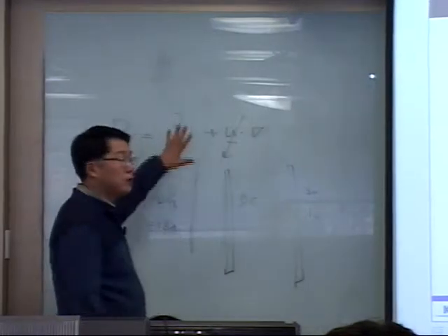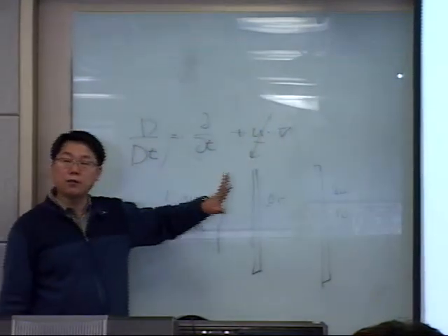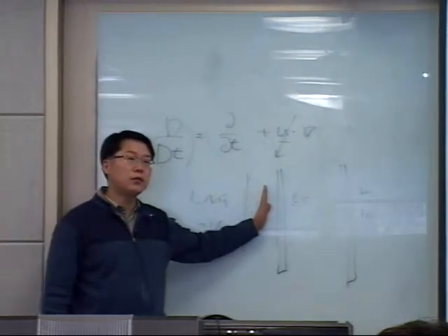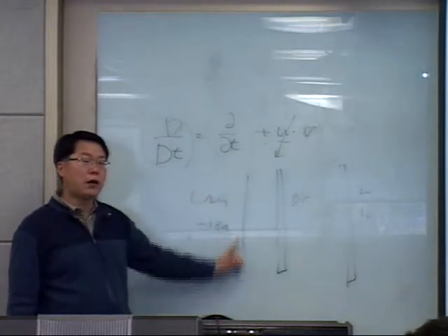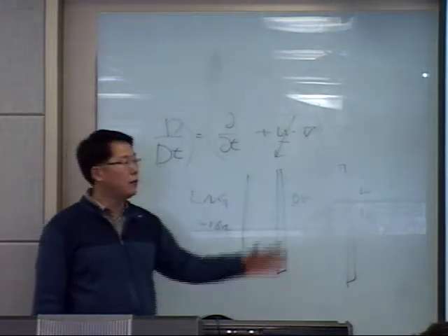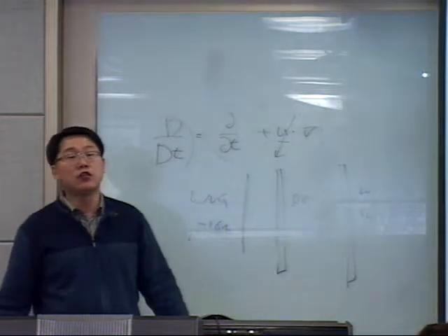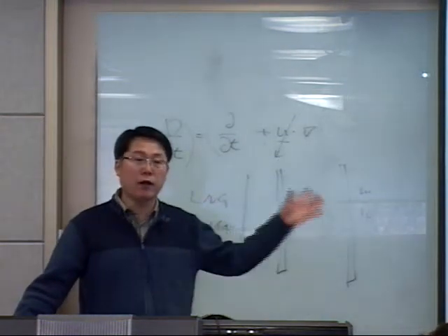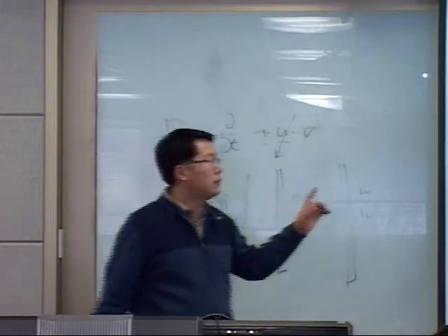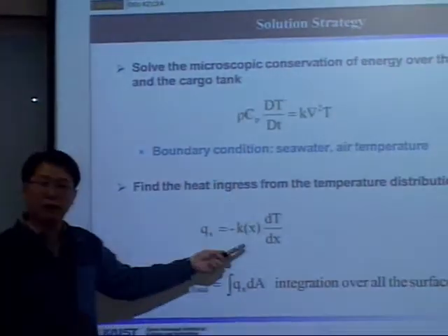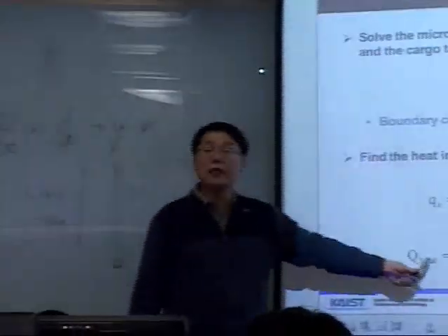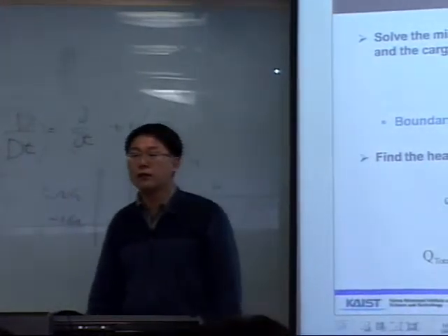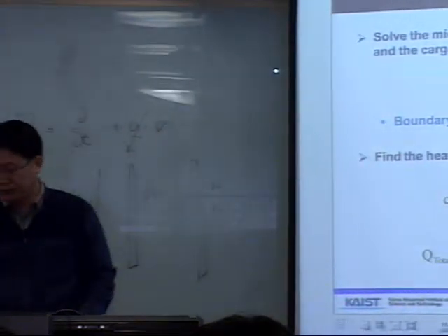You should know the inner structure of the ship, the inner structure of the insulation layer, and the proper boundary conditions. Then the structural analysis program will take care of the rest. It will solve this equation, calculate the heat flux, and integrate the heat flux over the surface. Any question?